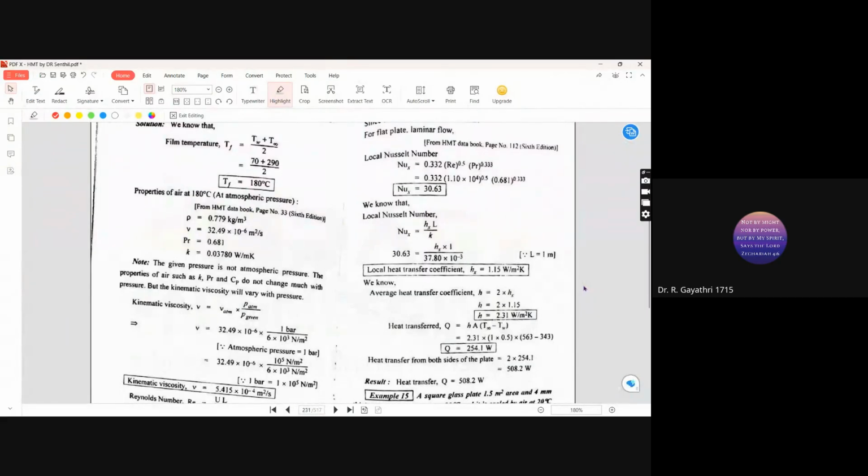Okay, we can use another equation. We can directly relate pressure times kinematic viscosity at the given pressure condition to pressure and kinematic viscosity at 1 atmospheric pressure condition. So they put P given times kinematic viscosity on the left side, and mu atmospheric pressure and P atmospheric pressure on the right side.